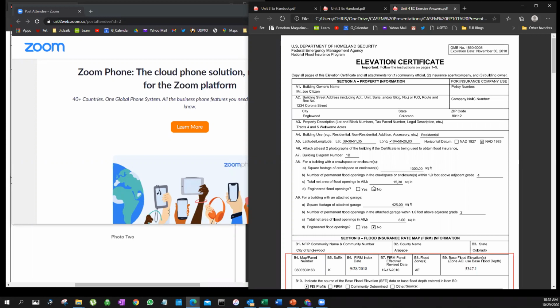There may be a question on proper openings, 1 square inch per 1 square foot used for parking, storage, and building access. Yes, and I have seen that question on the test. I had that question when I took it in 2000. Thank you for pointing that out.